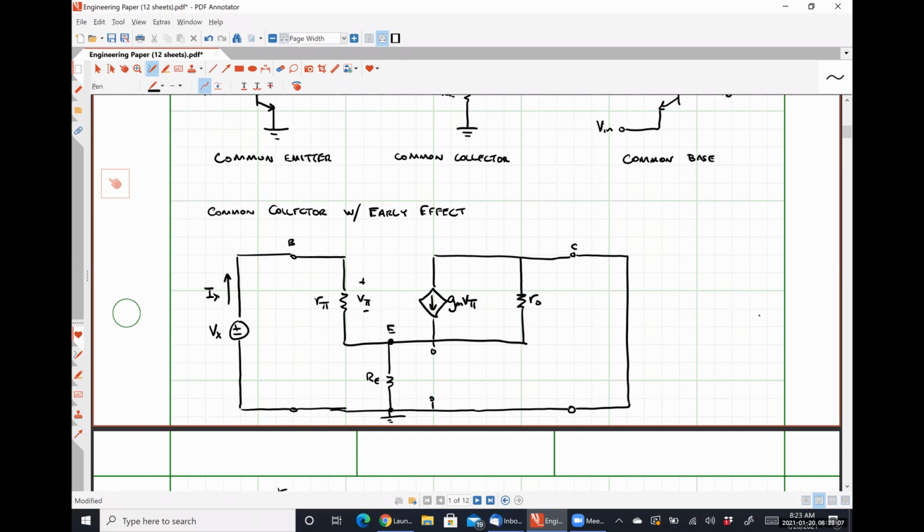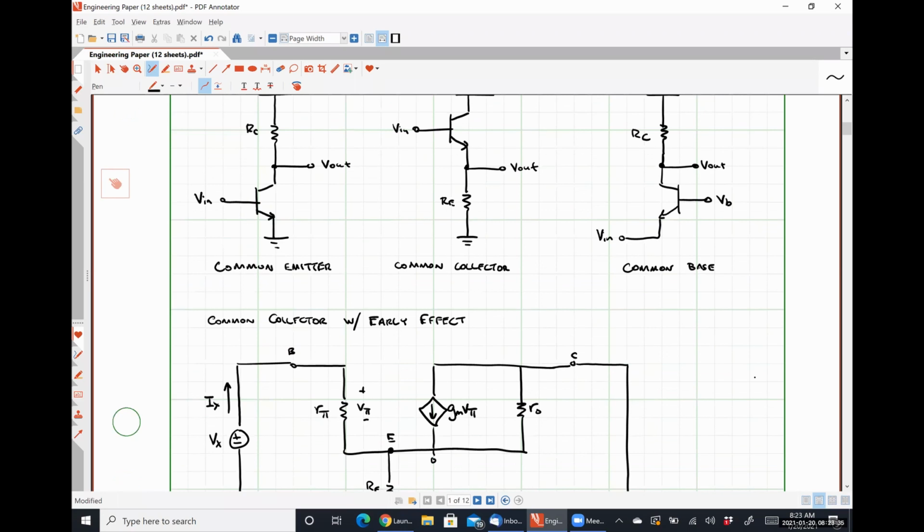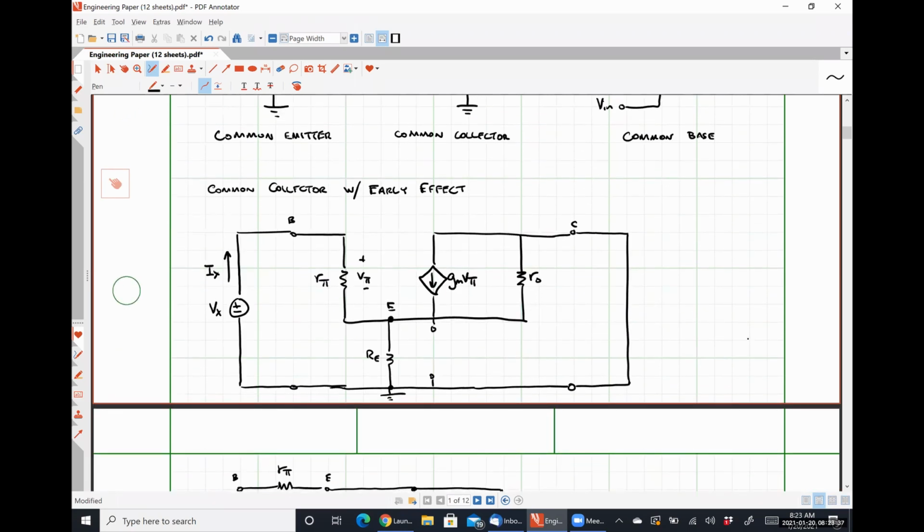I'm looking at a small signal model. So if I turn off VCC, that means I'm short circuiting that voltage to ground. So I'm applying the test voltage here at Vin, which you can't see my finger. I'm turning off VCC and then looking in through those terminals using a specific voltage, measuring the current, and then taking that ratio, okay?